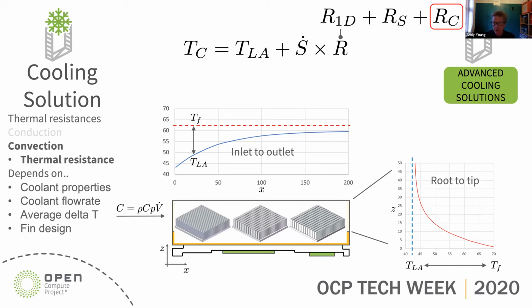The fluid has to decide, based on the balance of forces, if it's going to bypass or flow through that particular heatsink. More heat means more momentum added to the fluid, but these things are coupled. The heat transfer performance determines the buoyancy force that in turn determines the cooling. So all these things are coupled together in a complex way and can be packaged into this thing called effectiveness.